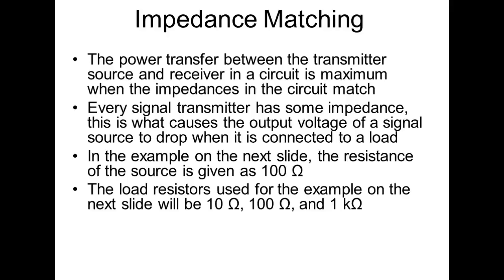NEC requires at least 6 inches from the edge of the box, not the back of the box, from the edge of the box. So when you hook up your plugs, you got to have at least what? 6 inches from the wall where it exits the box to where your wires are. Now why? Because of what? Yeah, if they run exactly what they need, we repair those things all the time.